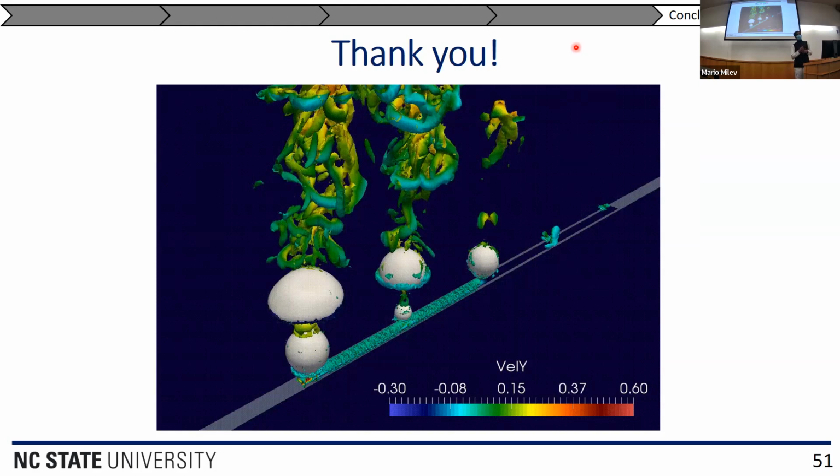From a plasma perspective, it essentially informs the frequency of these voltage pulses, so we're not zapping the water continuously. There's a frequency that we want to set. If we know how long the bubbles are at the electrodes, we have more leeway when setting up the frequency, and it's easier to match the voltage pulses with the bubbles hitting the electrodes. If they're there for ages, we can be relaxed and do 1 or 2 pulses every millisecond or whatever. But that's the discussion there. Thank you.